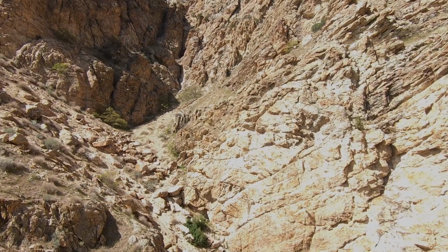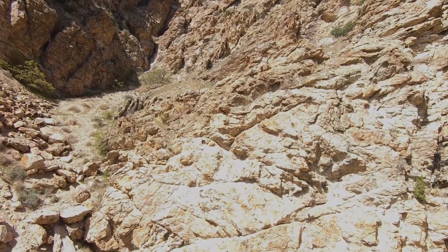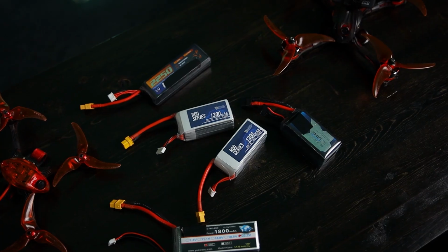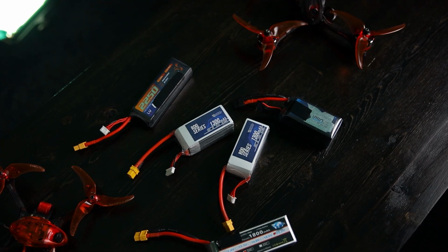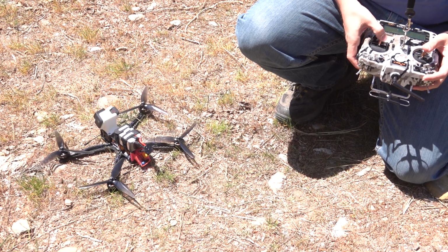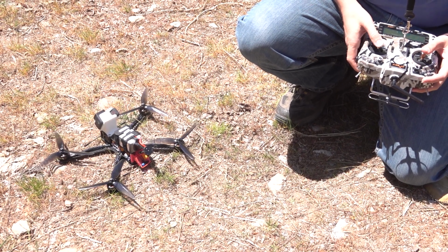Other sensors. Some flight controllers contain other sensors like barometers or current sensors. Barometers are used to measure air pressure and can record the relative altitude of your drone. This is used to prevent drones from going higher than they are allowed due to local regulations. A current sensor reads the power running from the battery and can provide useful information in your on-screen display. This is often used to know how close a battery is to being empty or how efficient motors are.